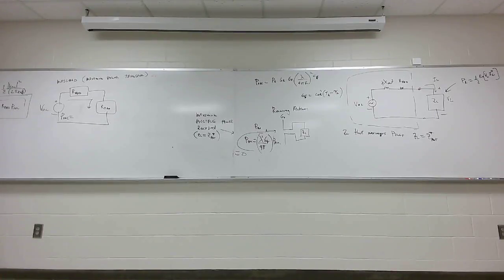You can actually measure it if you have no load on the antenna and you use a high impedance voltmeter. You will measure that value. Y'all hear me? But that voltage itself is best estimated using the P received times radiation resistance. That's the truth. Now, that's the ideal case.